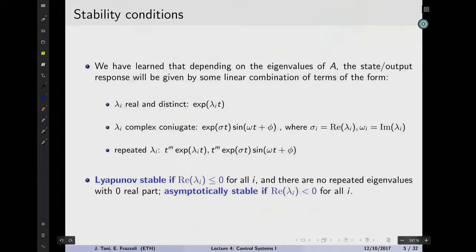So, very good. We now have outputs that we can describe of systems that we care about. We have a notion of what is the most important thing we care about, which is stability. How do we check it, right? How do we tell if the system actually is stable or not? And for beautiful linear time invariant systems, we figured out that we can tell if a system is stable by just checking what the eigenvalues of the A matrix are. We said, look, matrices can be diagonalized. If we had a diagonal A matrix, this would be the answer, right? Today we're going to see how we can diagonalize matrices. But let's get to the conclusion before getting lost in how we get there.